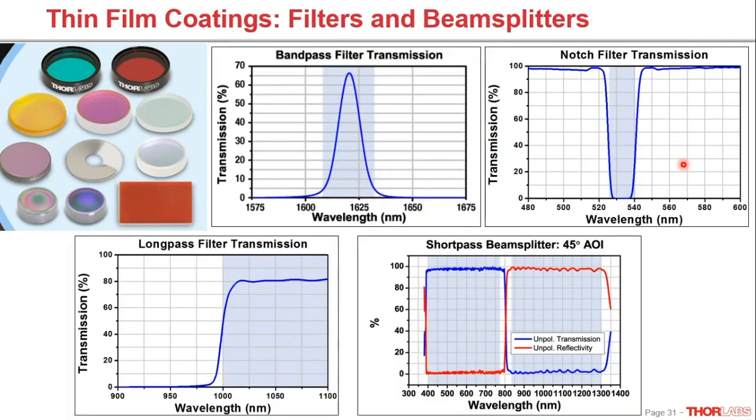Beyond that, we see various other approaches of design to these quarter wave and half wave stacks or near wave approximations there with much higher levels of thickness to achieve various other filters and beam splitters, which some of we see here, from the bandpass filter, the notch filter, some of our edge pass filters like the long pass and short pass, long pass shown here, as well as items that operate off of that zero AOI, in this case 45 degrees, with the dichroic beam splitters as well.